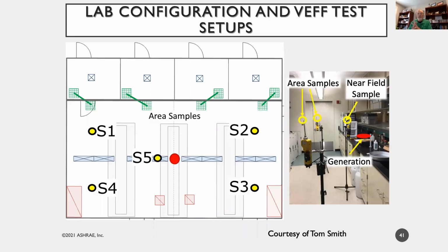So my friend Tom Smith, who does lots of laboratory work, was the chair who wrote the ANSI Z95 standard, and was even on the committee for the ASHRAE 110 standard, which is a laboratory hood testing standard. Tom is like a global expert on hoods. He said, okay, what's going on here? We're going to do some testing of what he calls VEF, ventilation effectiveness. We love acronyms in ASHRAE, and as engineers, we abbreviate everything. Ventilation effectiveness test. So we're going to do this lab configuration.